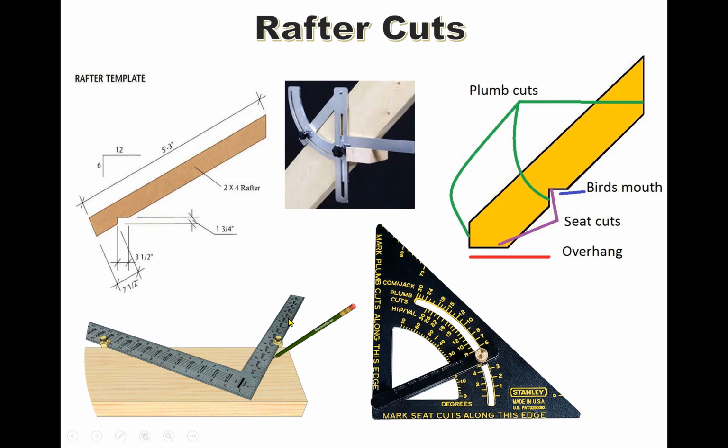So I'm going to tell you now how you would get the rafter to be cut so that when it is raised up and put in place, the roof is actually 27 degrees. So you may have seen on a drawing a little triangle, and you see a 6 at the side and a 12 up here. What that means is the pitch of that roof is 6 in 12. Now, in order to get the rafter to be at 27 degrees, or in imperial 6 in 12: the degrees is really for the metric environment, and the 6 in 12 is really for the imperial environment, because 6 inches and 12 inches.